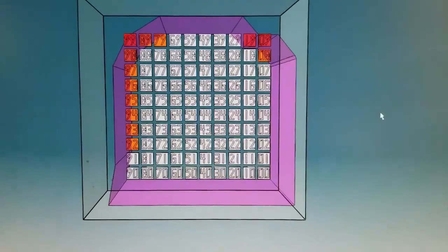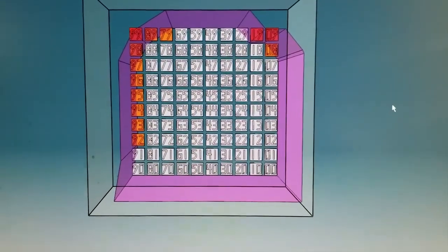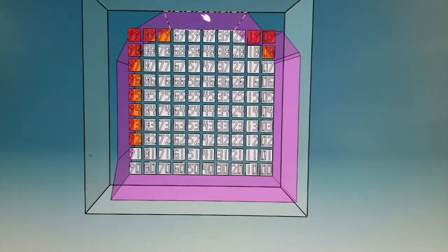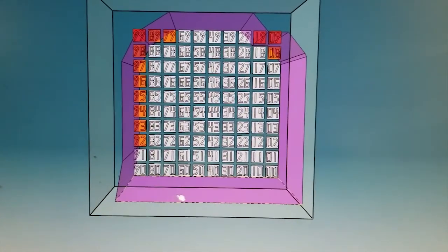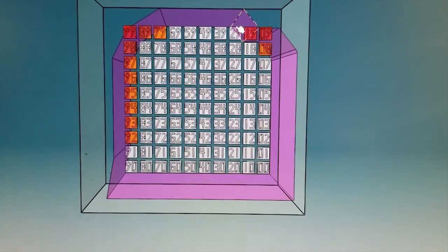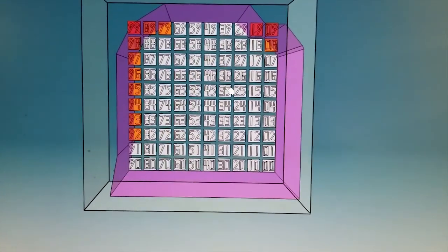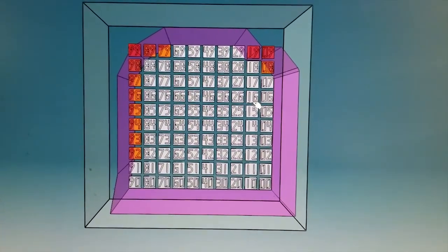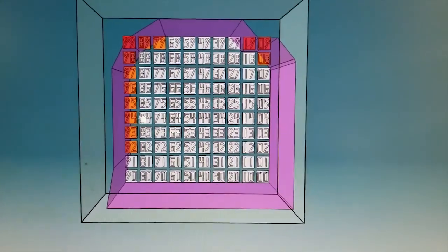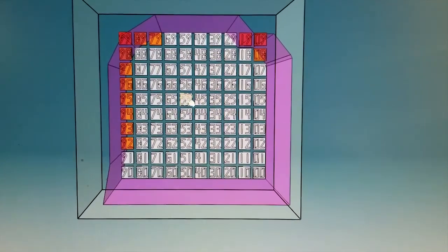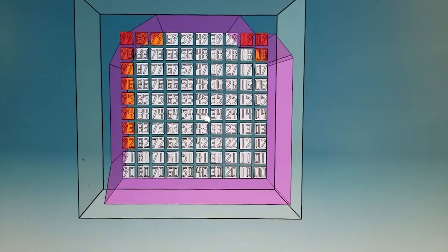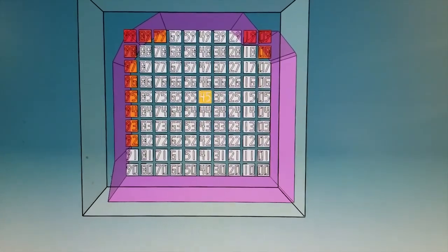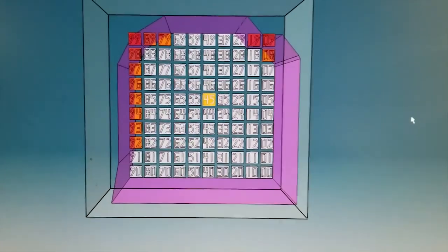In Sintratec Central, and also in Maya, I can situate all of my parts inside of this purple volume and know that I'm going to have good sintering at the temperature that I tested this at. For one of my largest builds, I did use a high temp so I could get a bigger footprint, but I did have some issues on 55, 54, 44, and 45 because it just got so hot in the center.